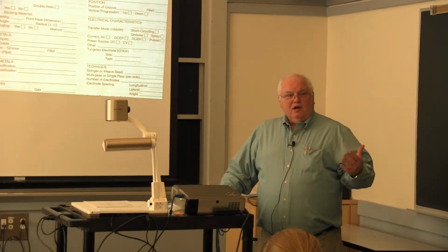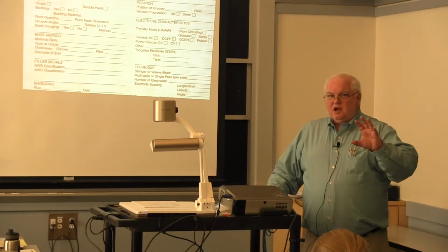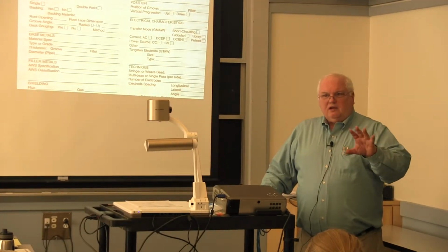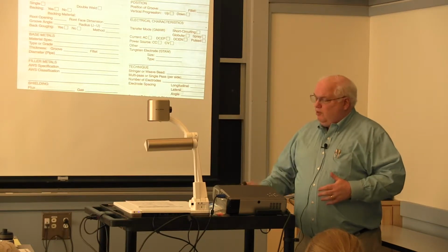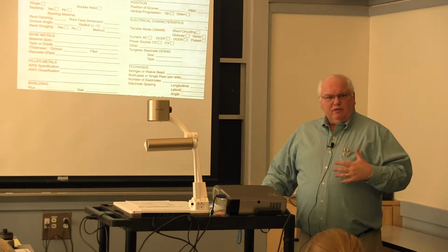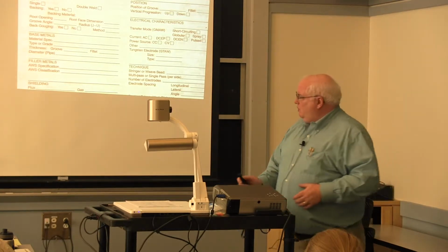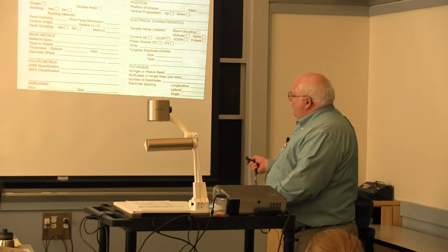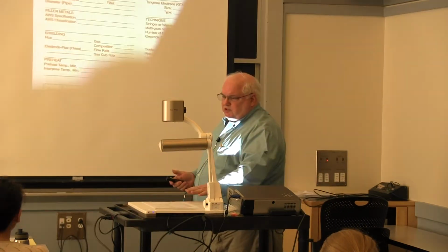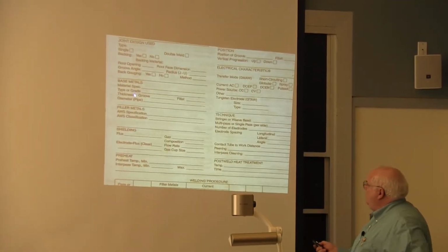The Boiler and Pressure Vessel Code didn't start getting these until about 10 years ago, when they saw that the American Welding Society was starting to make inroads on qualifications and PQRs by having ones that were universally adopted. And here are all the things that go into the recipe. Now, not all these things go into every recipe, and we're not going to take time, but